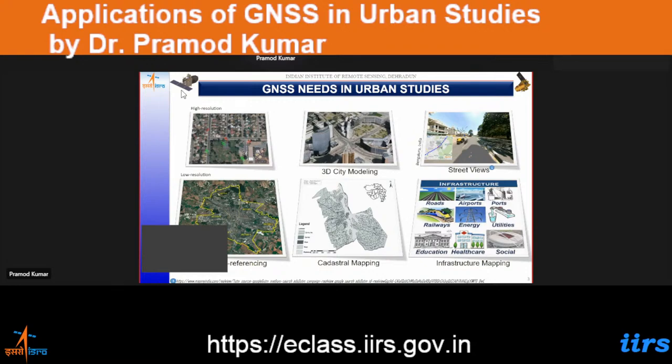So when you are working with urban areas and with remote sensing data, primarily the remote sensing data comes in standard format which needs correction, that is georeferencing. Now this georeferencing you can do either image to image, or if the other geo-rectified, geo-corrected image is not available, then you have to acquire the GCPs.